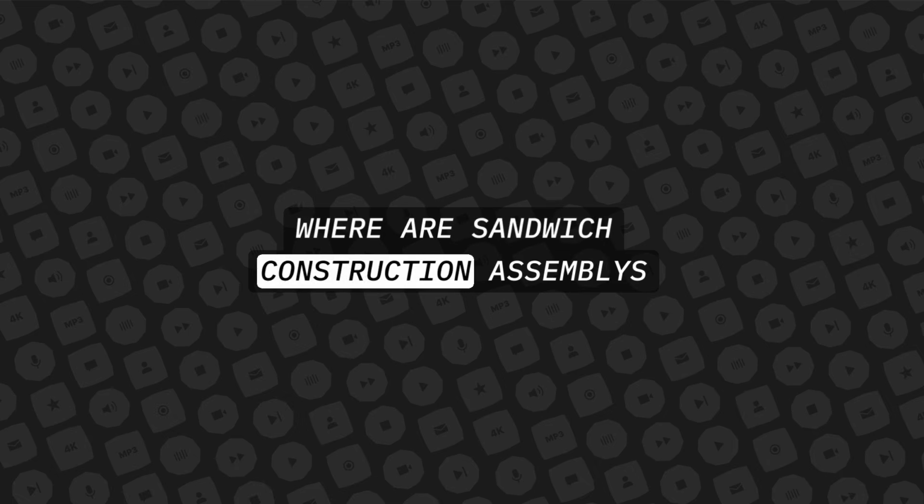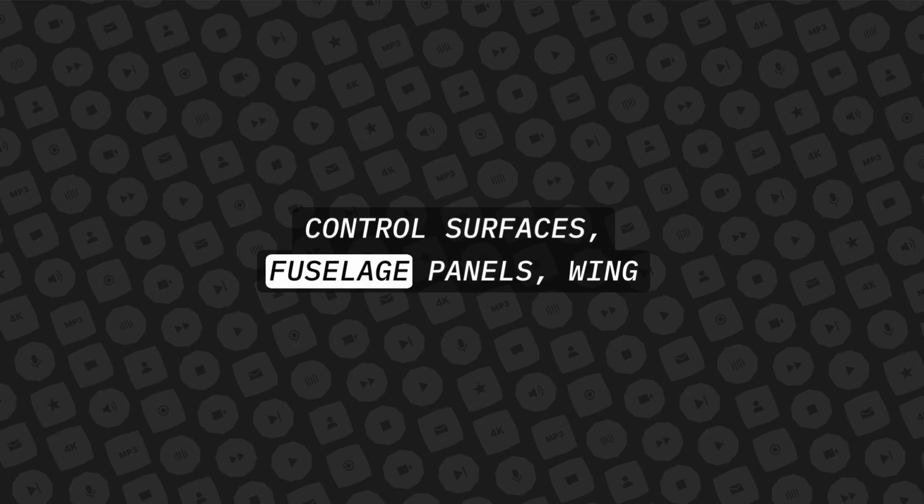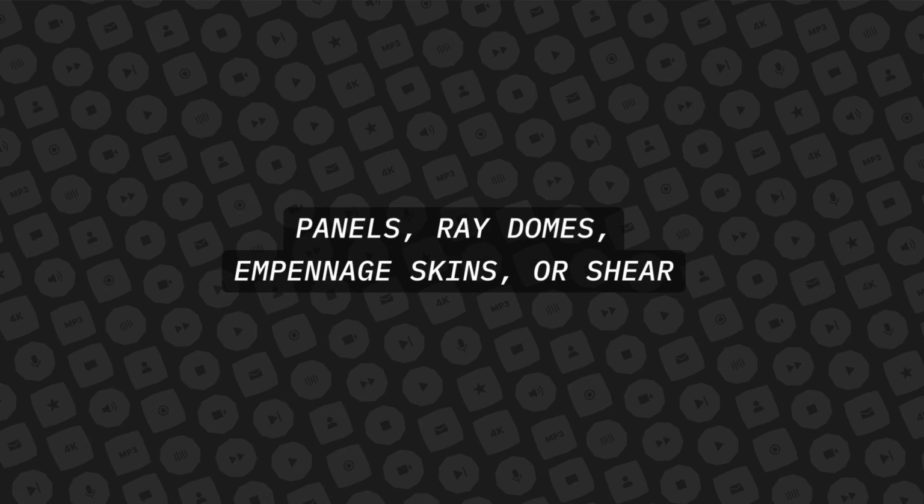Where are sandwich construction assemblies used? They are used for such areas as bulkheads, control surfaces, fuselage panels, wing panels, radomes, empennage skins, or shear webs.